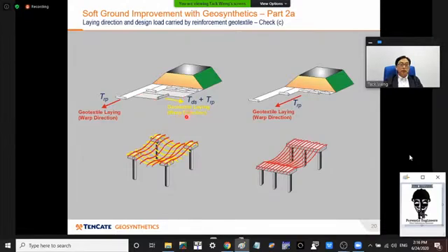So likewise, in the case of single pile caps, you need to be laying the reinforcement out in two directions, orthogonally to each other. And the reason for this is the geotextile reinforcements have a limited roll width, and even if it is equally strong in both directions, you need to be jointing the roll edges, and that weakens the strength transfer.